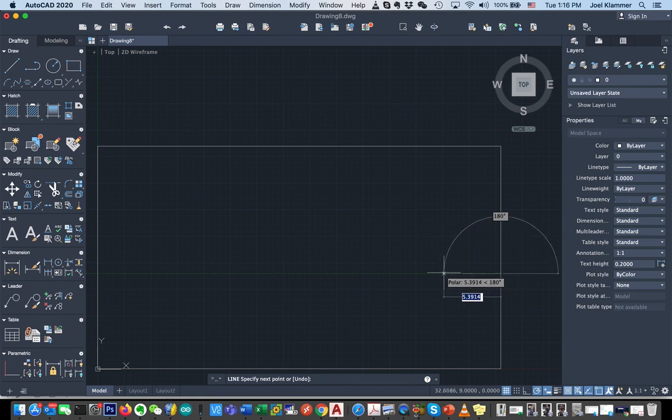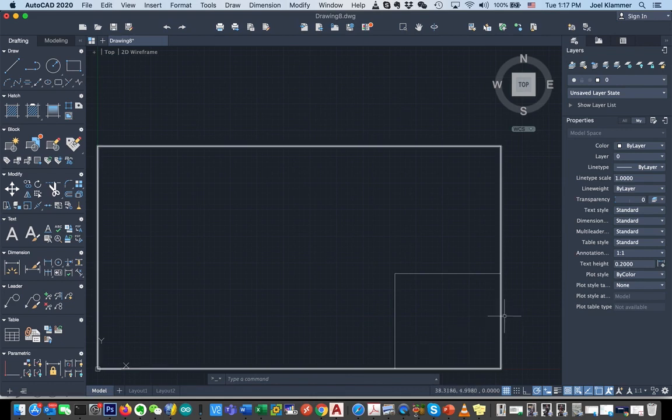And again, it starts doing the extension. And I need my garage to be, I believe, 10 meters wide. So I'm going to type in 10 here and press Enter. And then once I'm there, I'm going to go downward. And it automatically does 90 degrees until I get to the green X right there at the bottom. And I'm going to click to complete my garage. And so there it is. And I'm going to press Enter to end that line command.